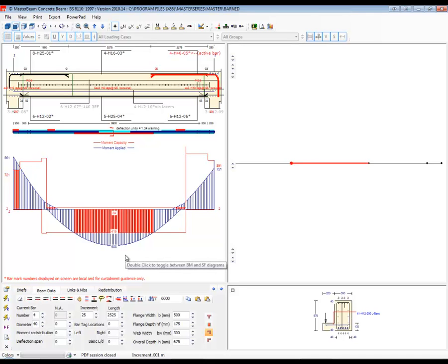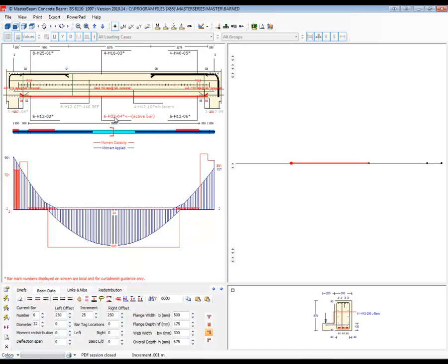So my solution would be to either get the load away and pull it in, or to decide that it's not got any torsion at all, or make the section squarer to resist torsion, because it's reducing my capacity. I'll have a quick play with it to see what I can do. I think that obviously we may need to go up to 6 bars and 632s. That's sort of solving a bit. And 40s is a wee bit of an overkill.